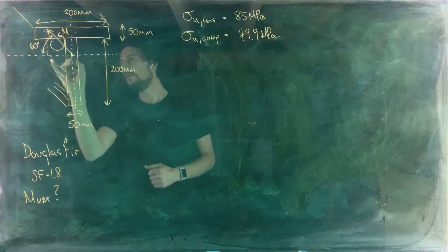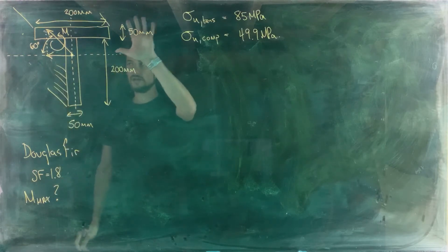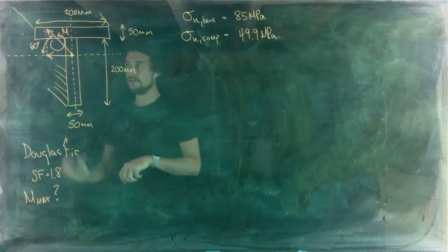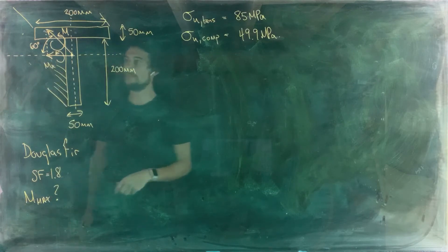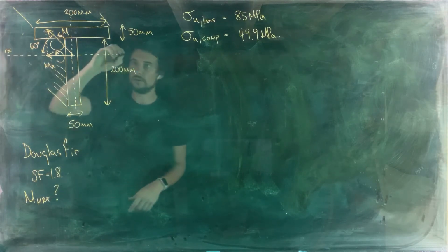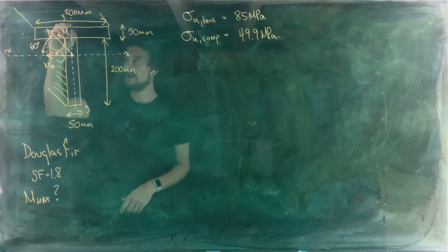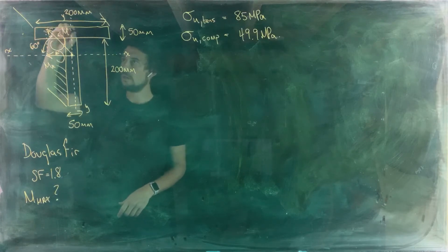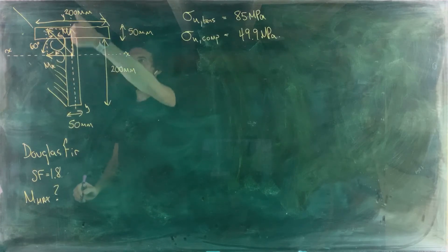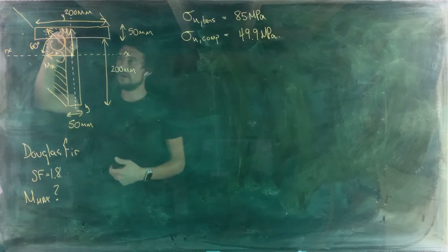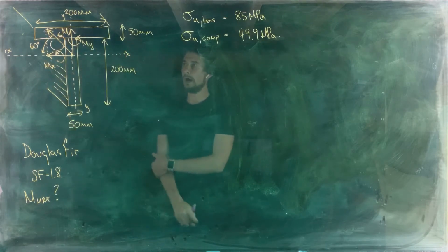So we're going to put the horizontal component down here. And again, you can use your right-hand rule to get the directionality of these correct. So we've got M subscript X for the moment about what I'm going to call the XX axis, and this would be the YY axis, and then the component along the Y axis here. Again, right-hand rule, thumb in the direction of the vector, fingers curl in the direction of the moment here. So M subscript Y.